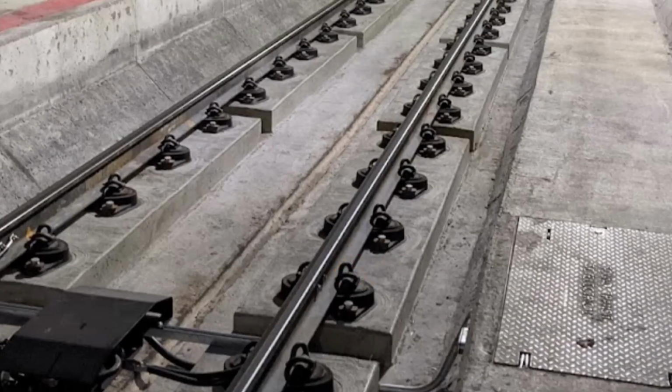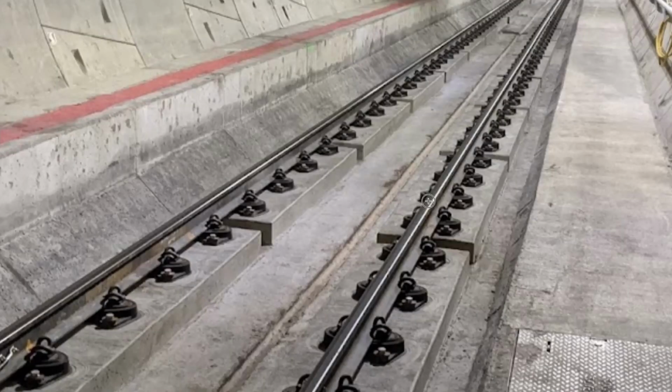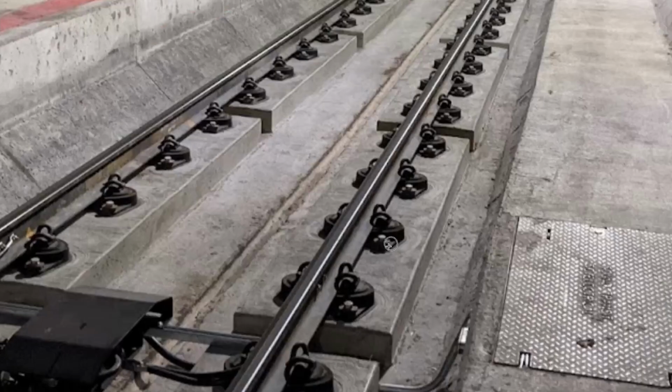These are kind of curly Q little clips that actually hold the rail in place, and they accomplish the task of both the spike and the anchor and help retain the rail down to typically a concrete tie, although in this case, this is what we call direct fixation track, which we will talk about in a little bit. But if you've seen a more modern built railroad or an electrified railroad like this one, you may have seen some things like this.